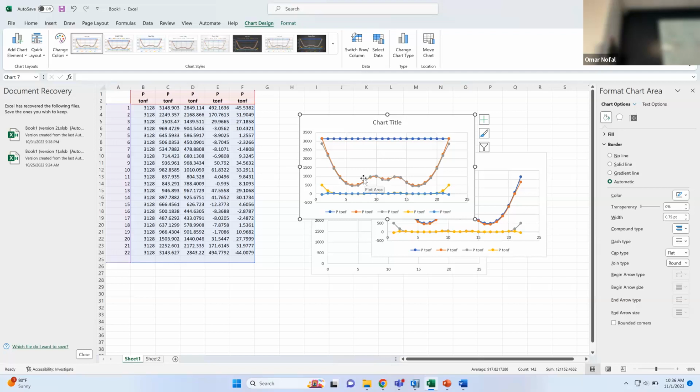The one that has 100% efficiency is the one that has a solid line, because all the columns, let's for example say we have a line of columns, all of them 150 by 150, and when an earthquake hits, the ones on the corners are taking most of the loads, and the ones in the middle are not taking as much load. So the ones at the corners are working at 100% efficiency, but the ones in the middle are not. So if we want to make it more efficient, we need to decrease this shear lag as much as we can.